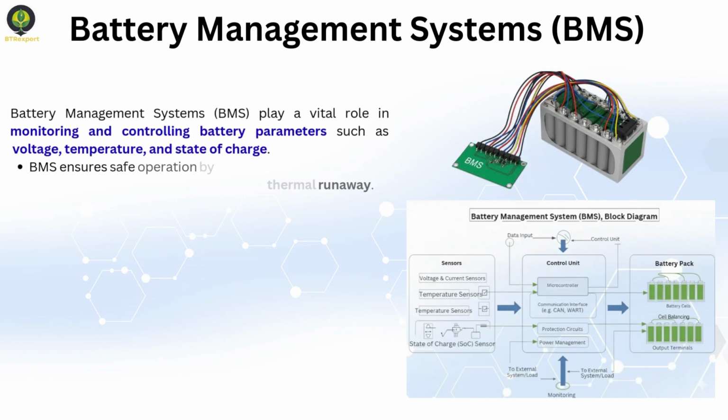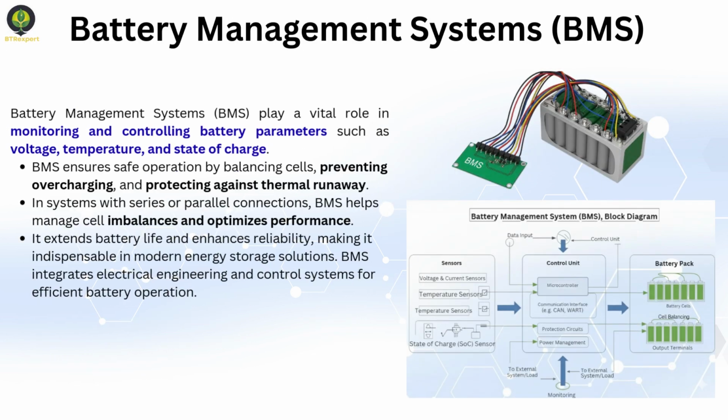Modern batteries, especially lithium-ion, require advanced safety systems. A battery management system constantly monitors voltage, temperature, and current at the cell level. It prevents hazards such as overcharging, deep discharging, or thermal runaway. Safety features include thermal fuses, cooling systems, current interrupt devices, and robust casings. Together, these mechanisms ensure that batteries operate efficiently and safely, even under demanding conditions.